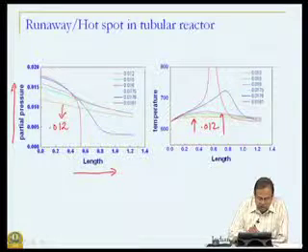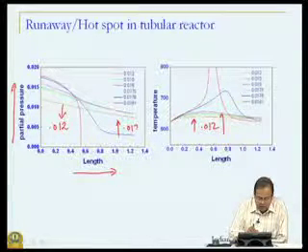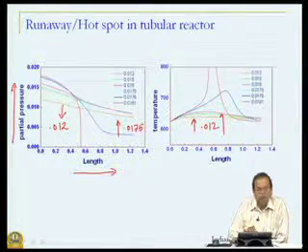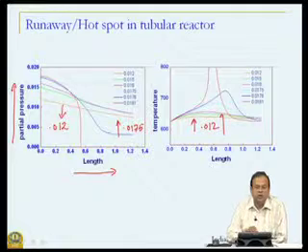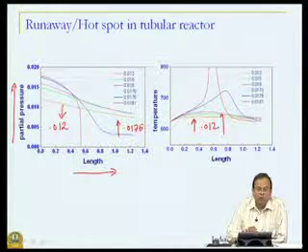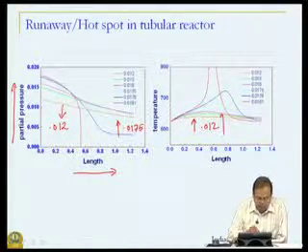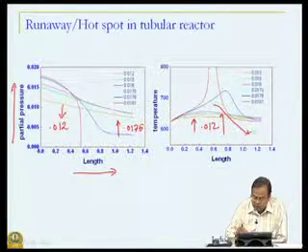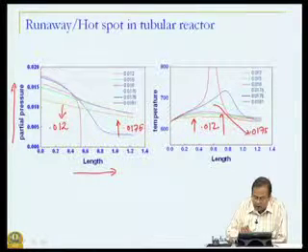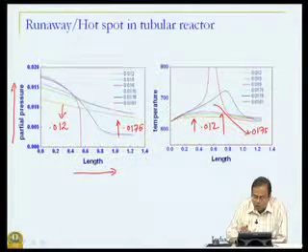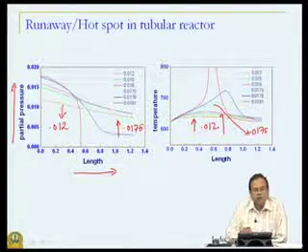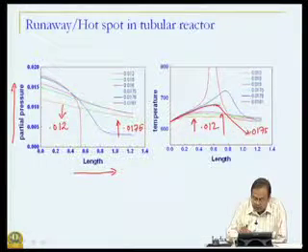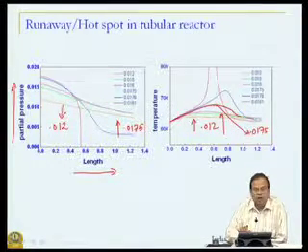For a partial pressure such as 0.0175, and notice the small difference that we are making. We are actually changing partial pressures now in the second or third digit, which implies the sensitivity of the process. We see that the temperature, for example, if you look at this result at 0.0175, has risen and given rise to what we can say is a small hotspot in the reactor. This is that line, in case you are not able to see it.